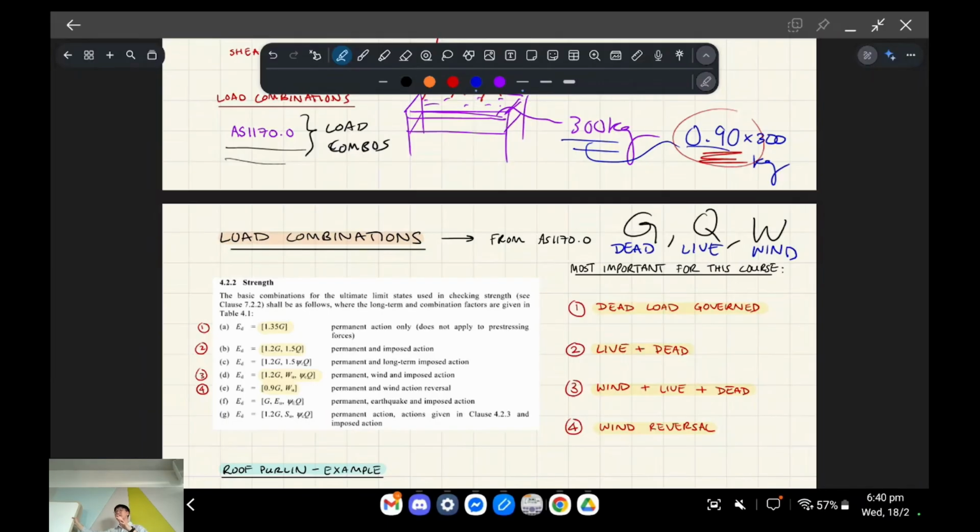Live loads, for example, in an elevator, the elevator you used to come up here: you could randomly have 20 people in there one day, or 30 people if you just cram a bunch of people in. That would be considered a live load because the fluctuation is much bigger. Any questions with that?